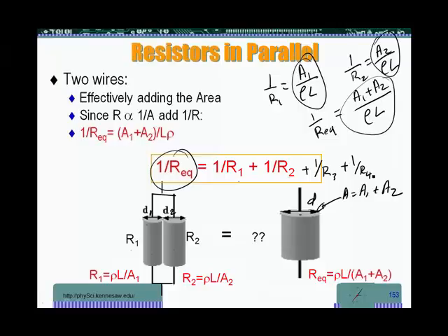Okay, so that's the idea. Why resistors in parallel? To find the equivalent resistance for resistors in parallel, we have to invert each one of them and add up the inverses, and then once we find the sum of the inverses, we invert that to find R equivalent. Notice also the equivalent resistance should be less than the individual resistors. It's essentially a highway with multiple lanes. A highway with multiple lanes has less resistance than either one of these since it has the same length.